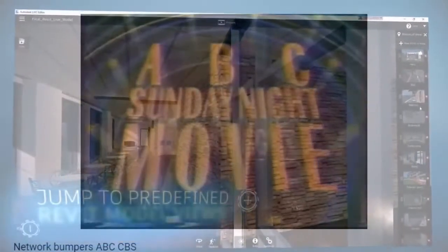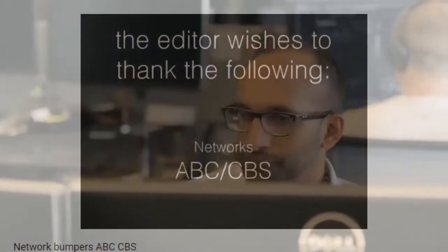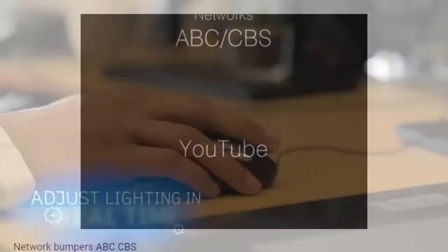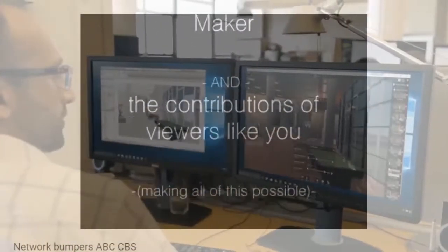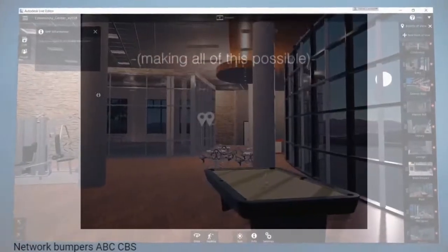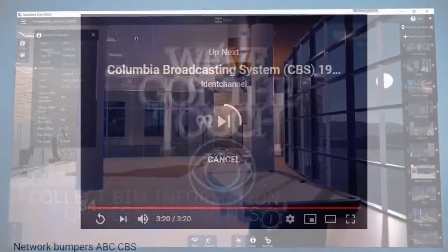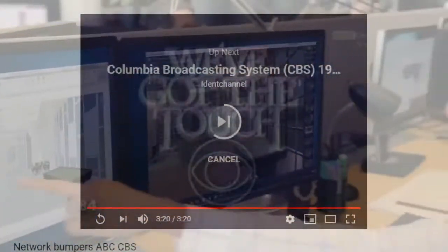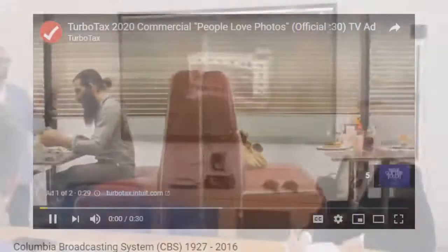I want to get this section open because you're going to see that some void forms, if they do not cut anything, will be deleted. To make a void form cut something else, use the Cut Geometry tool. Well, there's a reason: the void form isn't down deep enough. Minus 3 inches is where it's going to start down from the level. Let's give it an extrusion end of 3. So it'll bring it up flush to the underside of the floor, and this should cut it.